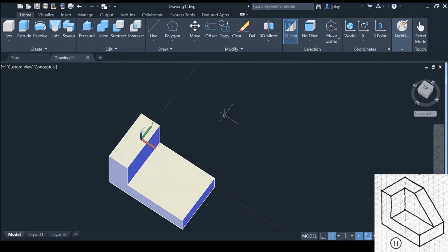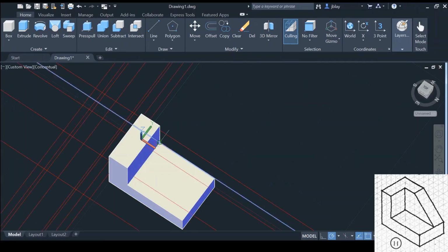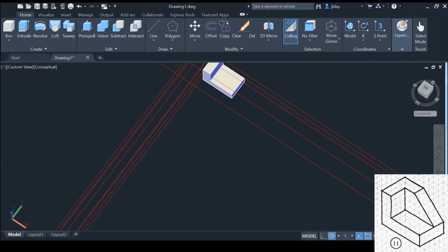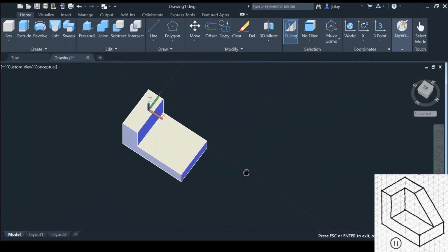Another option you could do instead of having to deal with that, if those negatives are very confusing for you, is you can draw some construction lines and kind of lay out this intrusion like I did with that first block. Then you don't really need to deal with negatives in your head. Uh-oh, I still have those construction lines from before. So let me go through and just delete all those because I don't need them anymore. Those were from when I did block number 1.